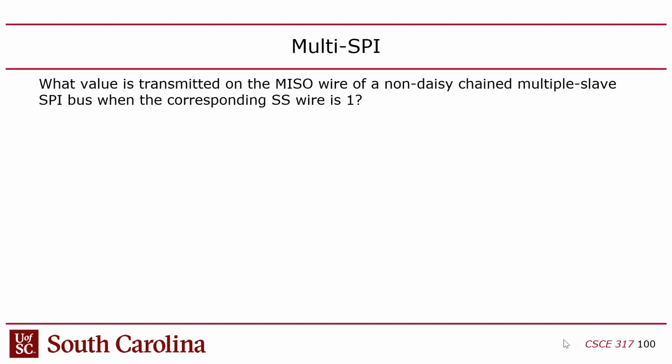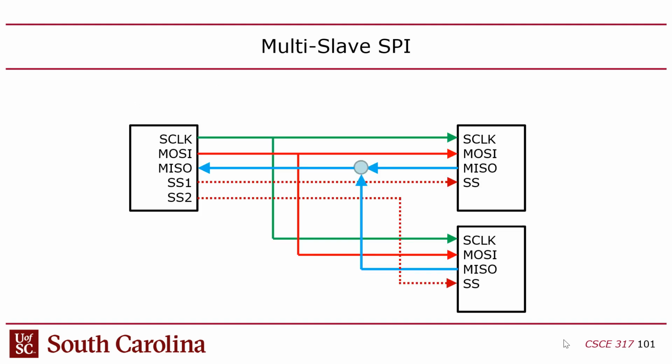Make sense? Okay, so UART is, in my opinion, even simpler than SPI, but it generally doesn't run as fast as SPI. SPI is in the megahertz range, whereas the fastest you can really run UART is 57,000 baud, and oftentimes even less. Okay, so let's go back to SPI.